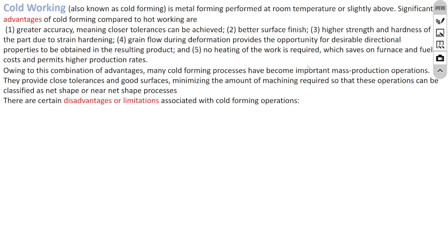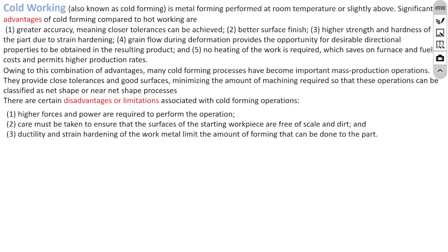But the disadvantage: at room temperature, in cold working, the material will be stronger, so greater forces are to be applied. Higher forces and correspondingly greater power of the driving unit are required.